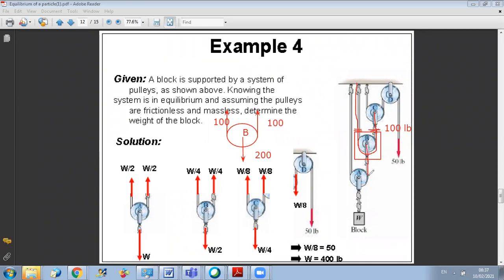So now I deduce that in the third cable, the tension will be 200. And this cable is going down, turning over pulley A, and then it's attached to the ceiling up. So here, what will be the tension in this cable? It is equal to 200. Now in a similar way, I know the tension in this cable.